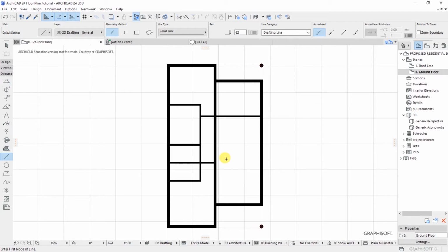You can use the zone tool, which will be a bit better because it will be putting dynamic information in your project, and you'll be working in a smart way, the one that is referred to as the building information modeling way, because you can extract these zones as schedule information that you can use for quantity takeoff.